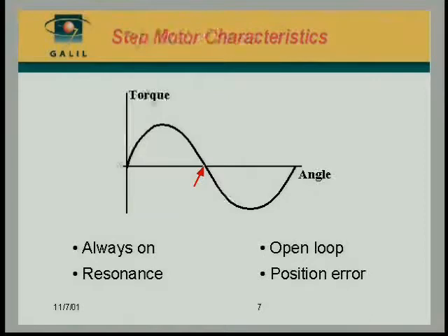This behavior of overshoot and undershoot indicates that the motor is going to be underdamped, and it leads to resonance. As a result, the stepper motor would tend to have a resonance frequency typically in the range of about 150 hertz, that it would like to overshoot at that frequency. And watch out, if you try to drive a step motor at that frequency, most likely the motor would oscillate and lose synchronization. That's a feature of a stepper motor when it's driven in full step.